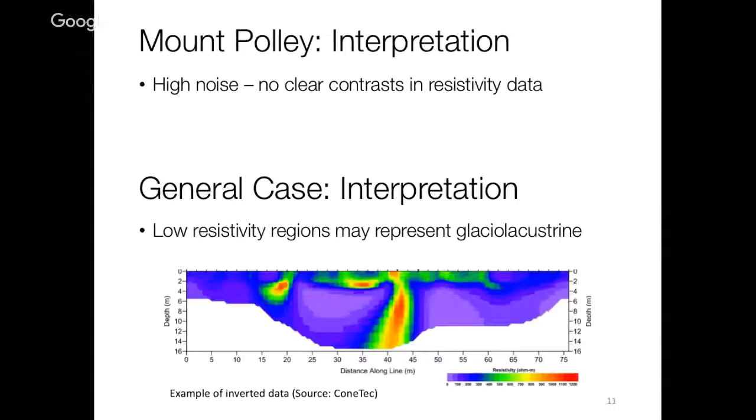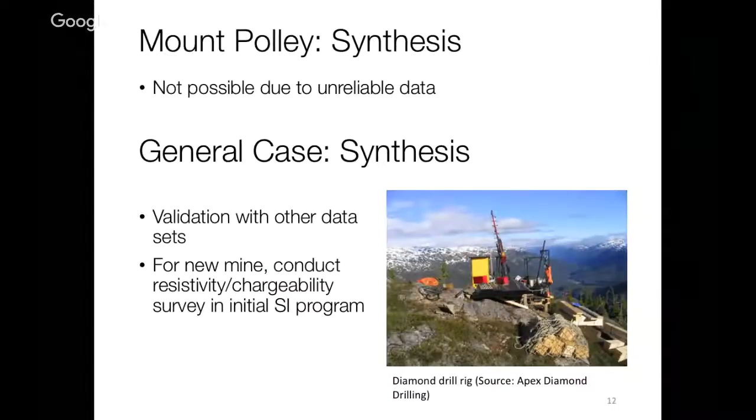So we determined that due to the high noise, high variability, and the properties being too similar at the surface, the glacial lacustrine layer couldn't be identified. So therefore, for better interpretation, we suggest that the geophysical survey be done when mining activity begins, so that the noise can be avoided. And to get a better idea of chargeability and low resistivity, we recommend that core drilling and other pore water pressure indications and other methods should be used to find the intersection between flow resistance.